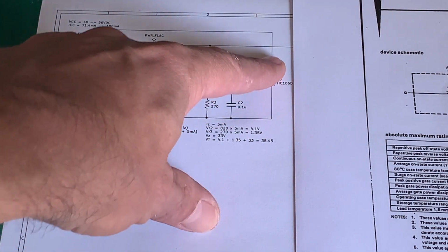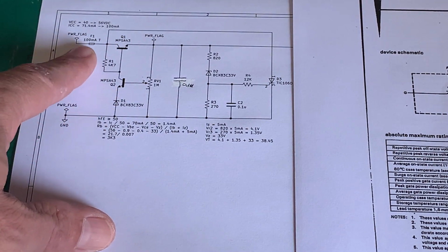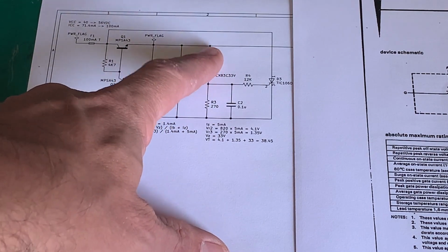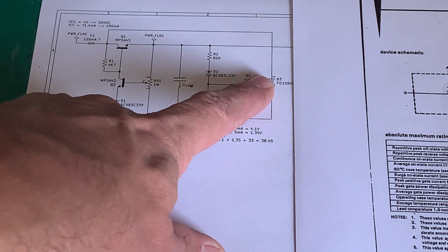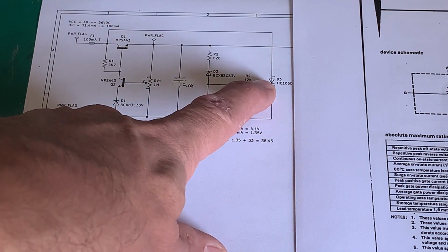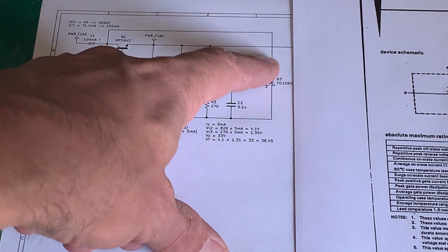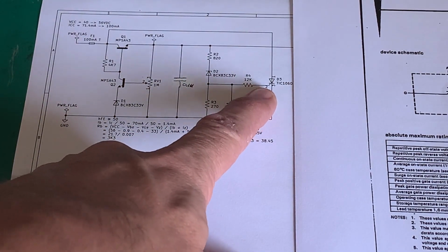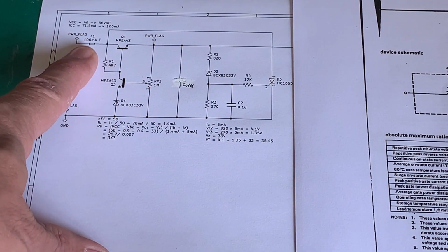So if we look at where we're going to switch, we take that line at the top, it's coming from our supply after the fuse. So if this voltage here goes up to about 38 volts, the Zener will be passing. It will switch the gate on. That will latch and it will pull power through the fuse to ground. In other words, it will create a dead short, a catastrophic short. And that is intended because what we want to do is blow that fuse.